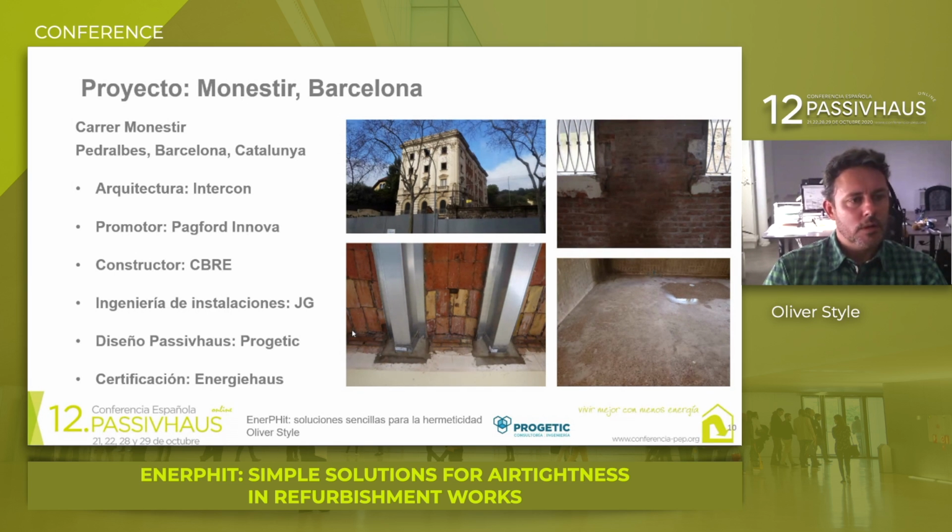Part of the ground floor is in contact with ground level, and the facade comprises double-row manual brick, 29 centimeters, with artificial stone blocks on the north and south facades, and part of the more elongated facades from east to west, where the facing brickwork is visible, as shown before. The floors and roofing were made of precast concrete joists, reinforced at the beginning of rehabilitation, as evident in the photograph, with ceramic vaults and 3-centimeter terrazzo flooring.